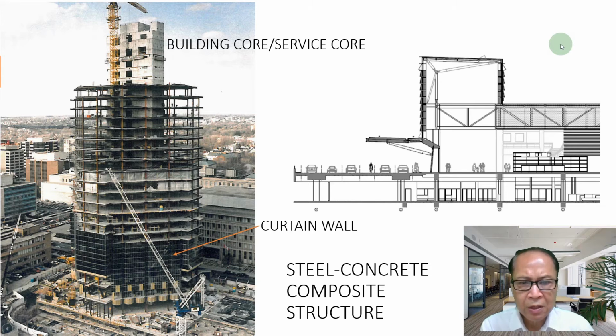Okay, after the concrete construction, the monolithic concrete construction, we have the steel concrete composite structure. That is made of concrete and steel frame, like this one, with the concrete core. Here the concrete core, surface core, encloses the lift shaft, the lavatory, the air conditioning room, and pipe duct, etc. Mainly for the surface, the floors and steel decking.